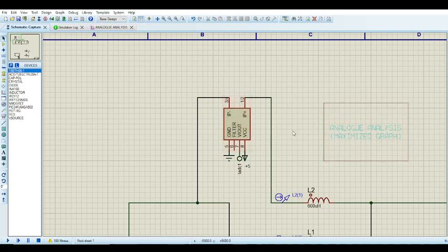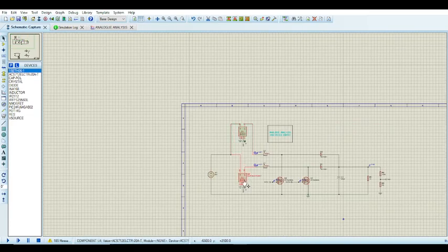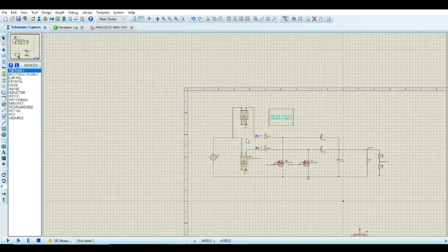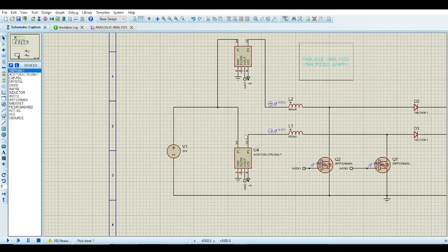Personally, I don't get too obsessed about how high the efficiency is, so I like to use shunts here so that I can control the current going through here better. But it's a choice. If efficiency is a huge concern, then you probably should just go with the Hall effect here and deal with the inaccuracies. Well, not inaccurate, but not super precise, right?